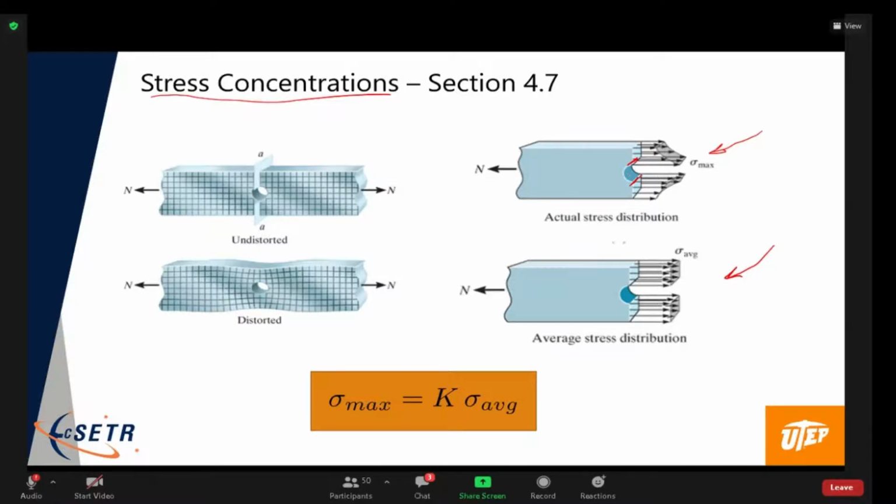Because you have a sharp corner there, you had another stress concentration and the stresses jumped up significantly. Obviously, one way you can handle this is to do the finite elements and see what those stresses are. But historically, that wasn't always an option. There is a pretty quick way to solve those, and that's with stress concentration factors.